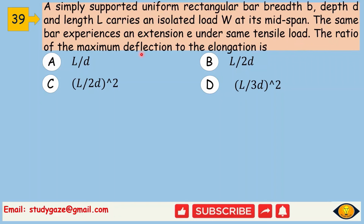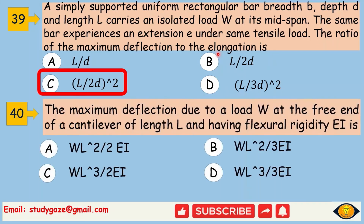The ratio of maximum deflection to the elongation is L by 2d whole square. Next, the maximum deflection due to the load W at the free end of a cantilever of length L and flexural rigidity EI is WL cube by 3EI.